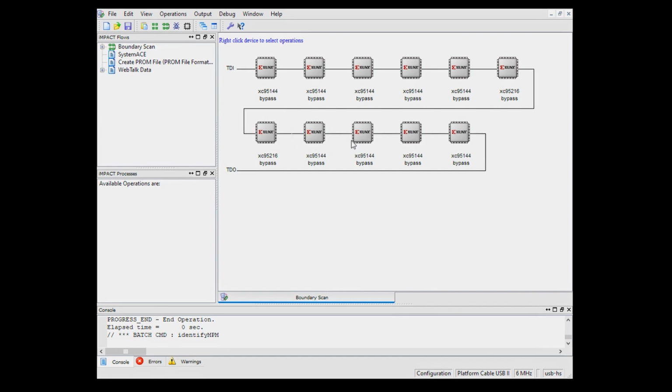I'm having this iMPACT running on Windows 10, and it is having very much difficulty reading back the firmware. If I try to do a readback on any of the PLDs, this whole application will crash and exit. So for some reason I cannot use the iMPACT GUI for reading, but there is another quirk. I can use the command line to read and write all of the FPGAs. I can read all of them and write all of them except for the first one in the chain.